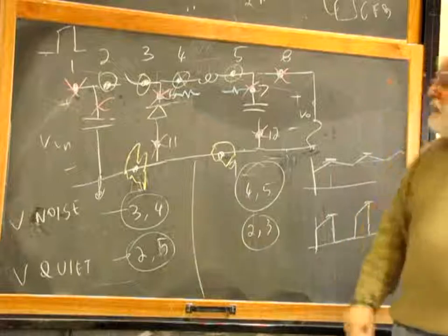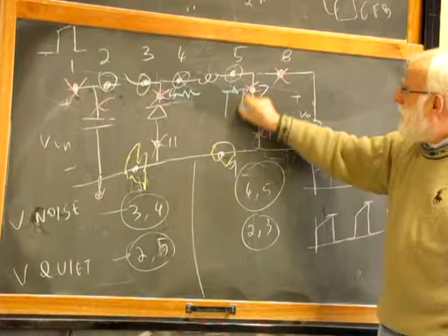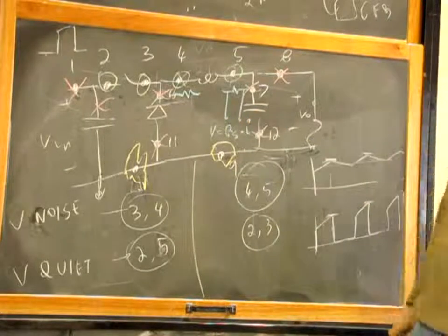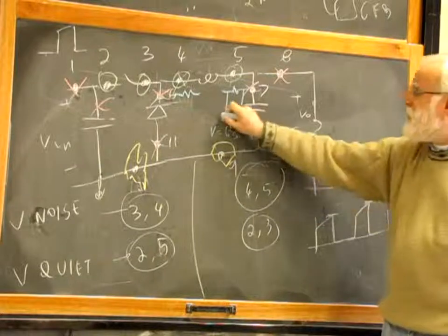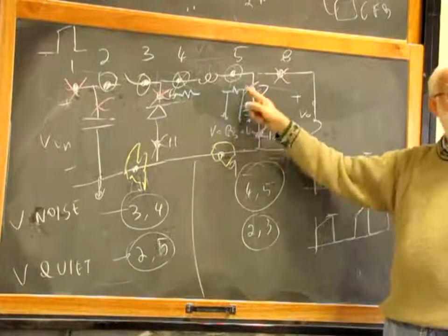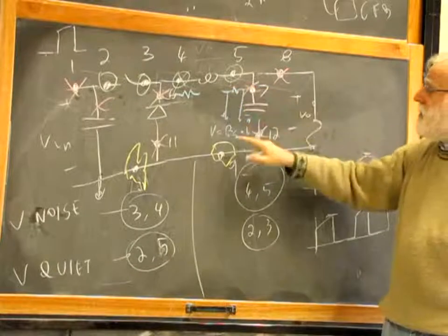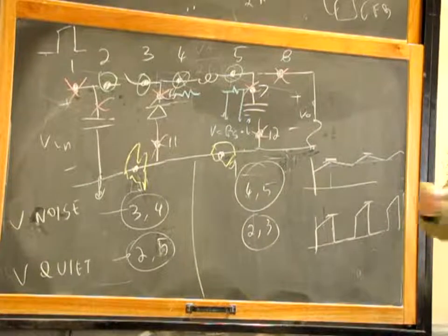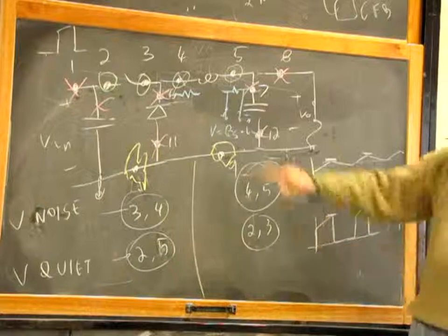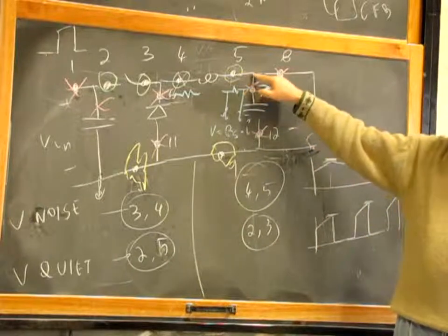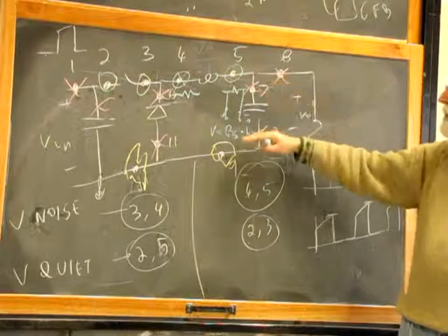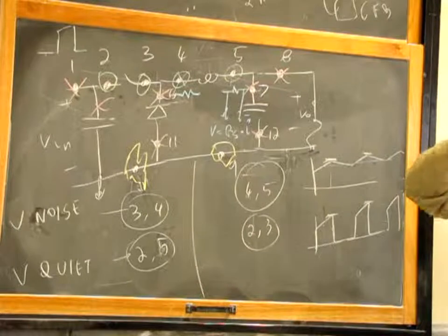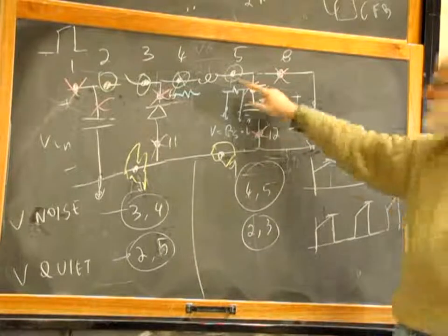If you put a resistor over here, you have a voltage drop V equals RS times I, and this is the differential voltage across the resistor. But if you want to evaluate not only the differential voltage, but also the common mode voltage, the average voltage of these two nodes, you see that the average voltage over here is about the output voltage, constant, DC. So you can use a differential amplifier that does not sense this common mode DC voltage, and this is a good place to put your resistor.